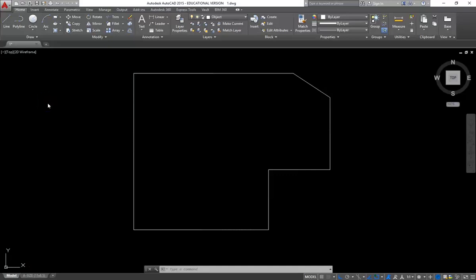Unit 4, Basic AutoCAD Operations, video number 2. Using our guide plate drawing on page 1-18, we will continue drawing the guide plate by adding 2 circles inside the object. To do this, we will need to incorporate our offset command as well as our circle command.